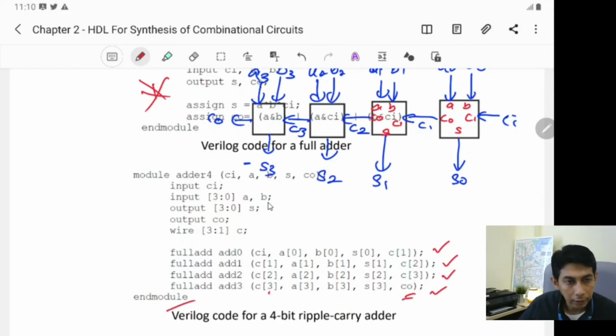So by doing this, you will now have the 4-bit adder. When you have another one, you can have a 5-bit, 6-bit, or any bits that you want. All right. So this is why the hierarchical modeling design methodology is very important, right? So you can always reuse your design to create a bigger design. And this is how design engineers design a complicated circuit.